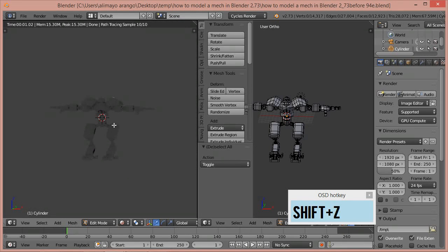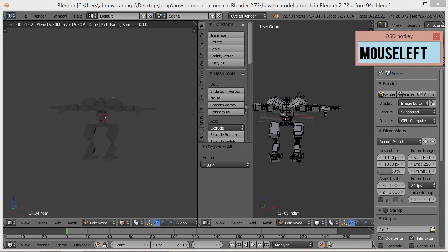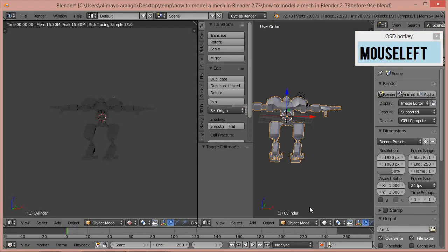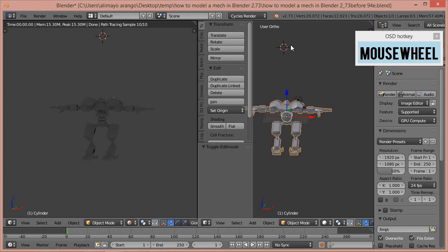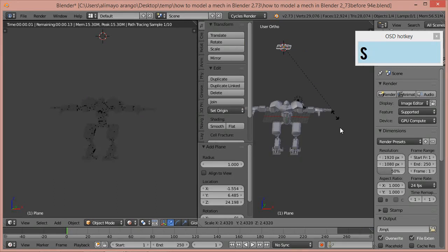And this looks like this now because there's no light. So what we're going to do is click here, go to object mode, right click here, wherever your 3D cursor is at. Objects tend to come in to where your 3D cursor is at. You're going to press Shift A, bring in a plane, press S to scale.